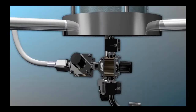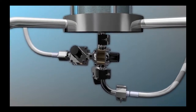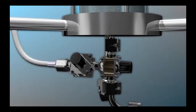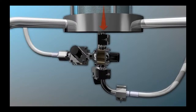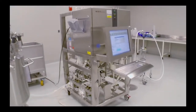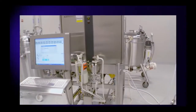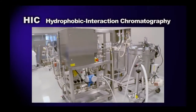The UV optical density sensor, which measures protein concentration, indicates when product begins eluting from the column. At this point, outlet valves are switched to allow flow of the eluate, the product stream, to a collection vessel. When the UV sensor indicates that all of the GFP has come off of the chromatography resin, the outlet valves are switched to waste. When all of the eluate has been collected and pooled, the anion exchange chromatography step is finished, and it's time for HIC, hydrophobic interaction chromatography.